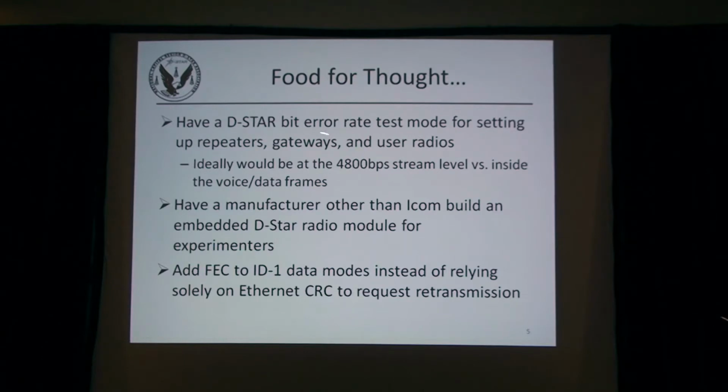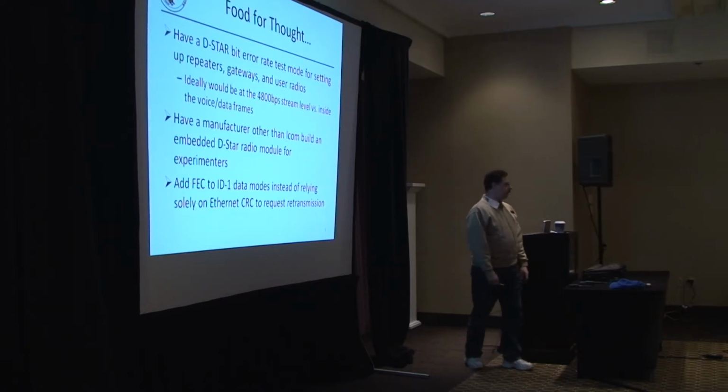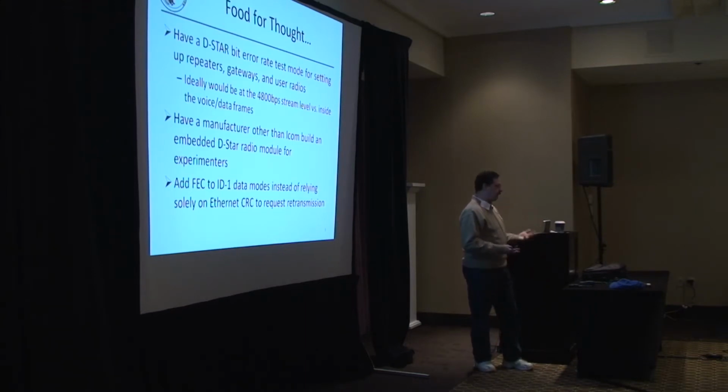But you ran into this problem as far as, well, how do I split the problem and figure out what's going wrong? And unfortunately, in all the D-Star stuff, they don't really have any sort of test or diagnostic modes, as strange as that sounds. They have a jack or a USB port in the front that you use for programming the information, but they don't have any diagnostics at all.